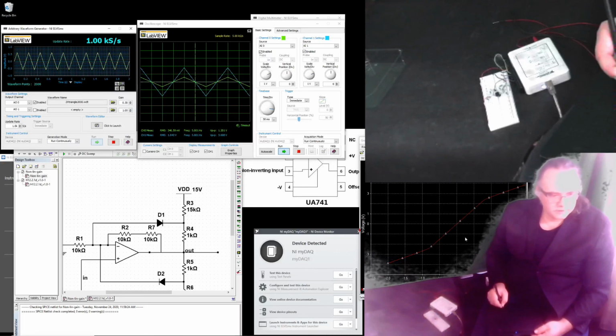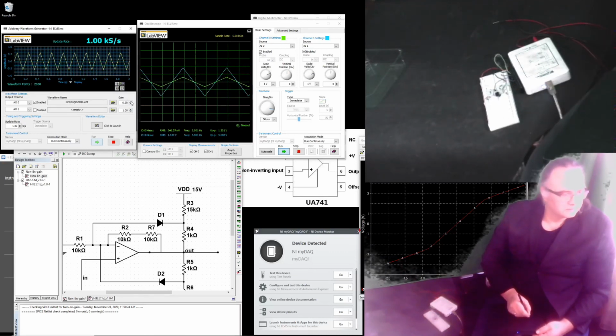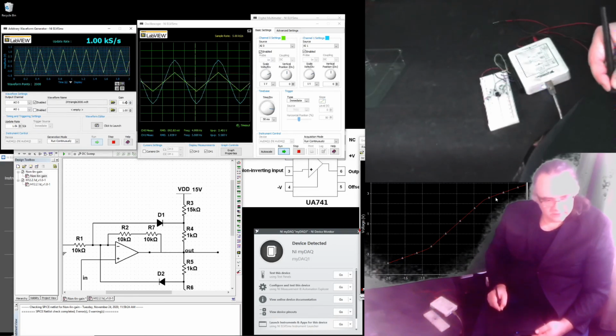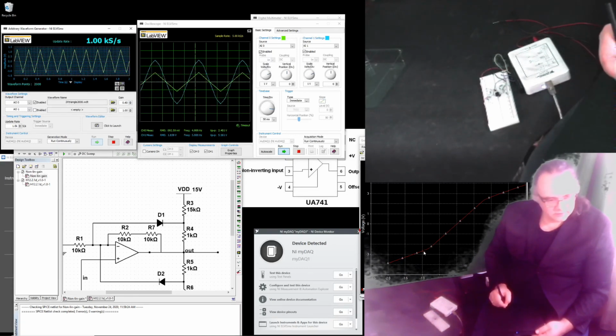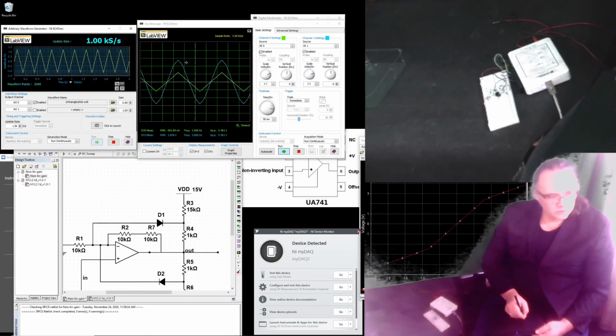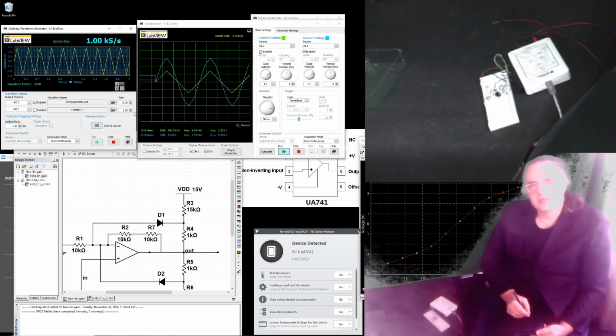Now my input signal is in the linear characteristic here, and if I increase it further, the peaks of the output signal exceed these points here, and I have the compression, the nonlinear gain. This is where my gain reduces.